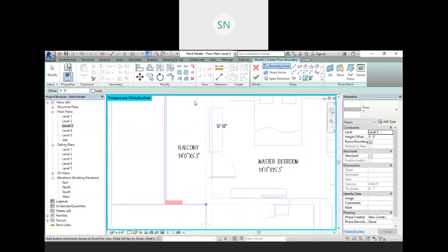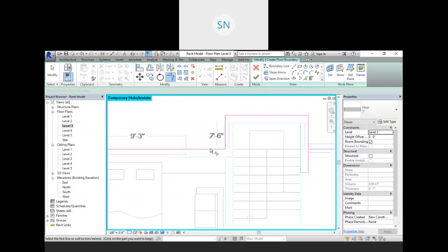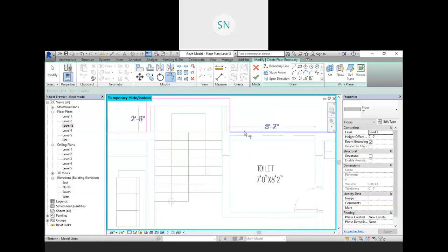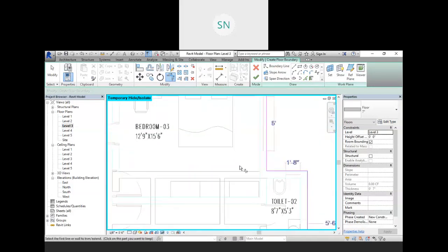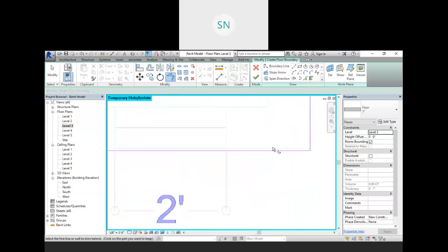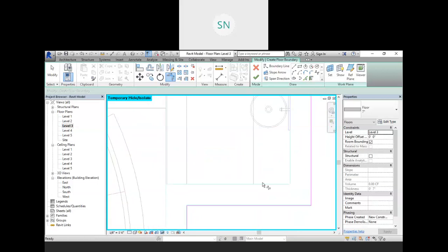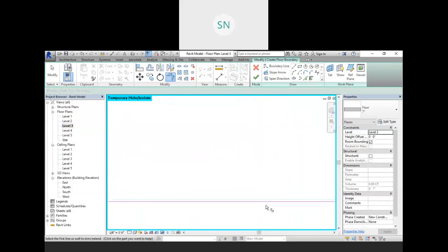So we have created all around geometry. Now go to the corner and make sure everything is properly in contact. We have to align all this geometry because the proper snapping is not done over here. So click on align.